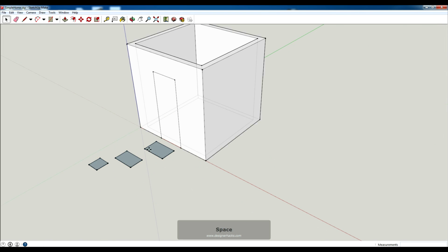What you can do is take this one, I'm going to say 1 inch here. If I double click on this face, it'll extrude that down. So all of the faces that I double click on after I've set my 1 increment will extrude 1 inch. So it's helpful for quickly extruding a bunch of different things at the same distance.